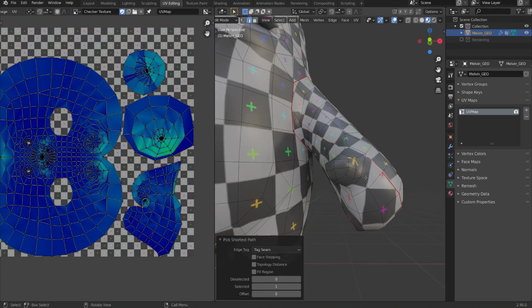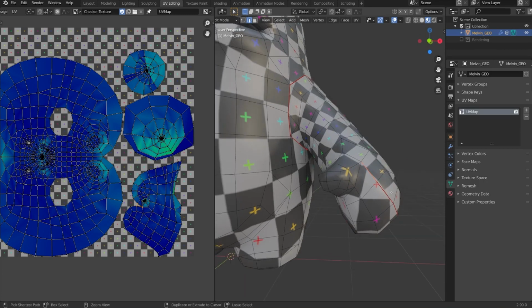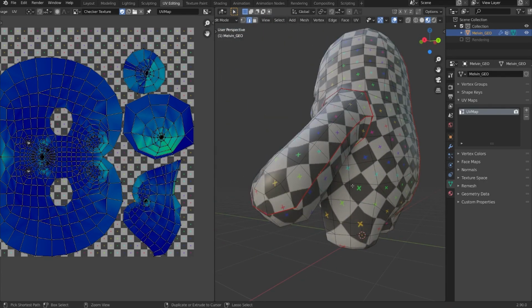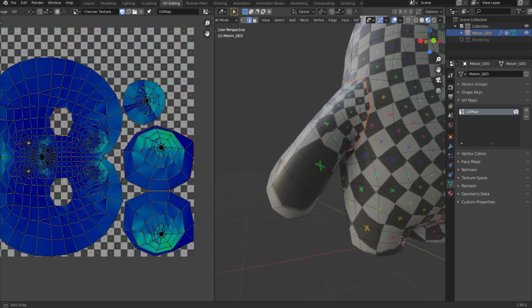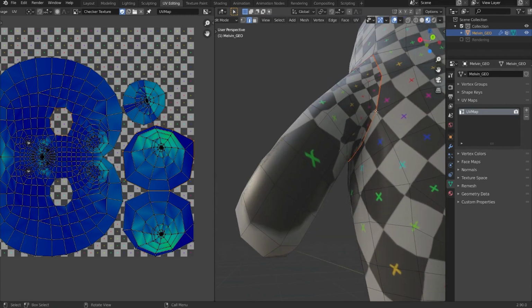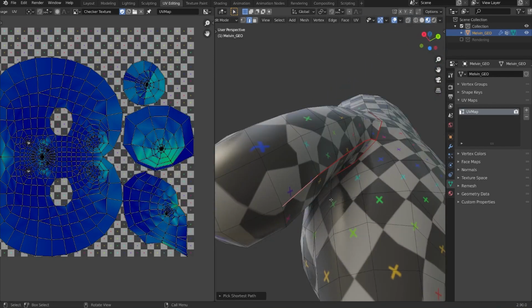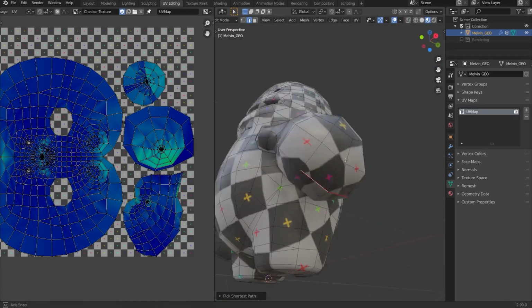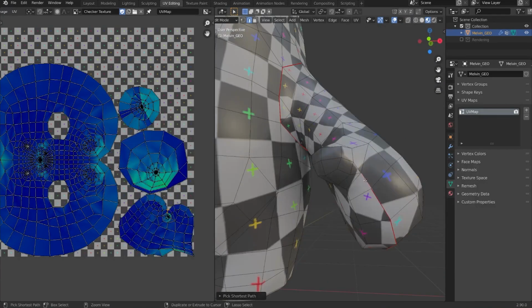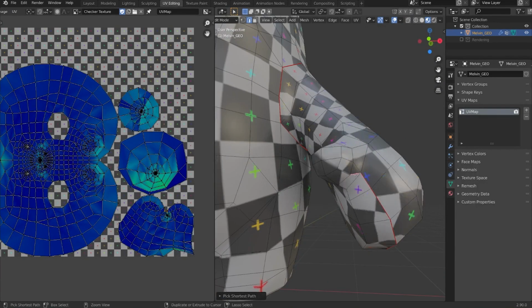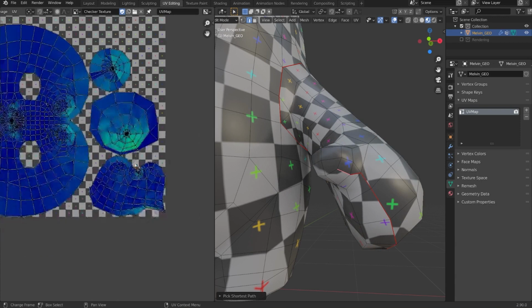Otherwise, we're going to have to make a ring around the thumb, and I don't want to do that. So I'll hit Control Z and undo this, and instead, let's try the edge loop right below it. Again, I'll select that one, hold Control and left click, and bring this up and around. And now I can bring this up and towards his thumb.